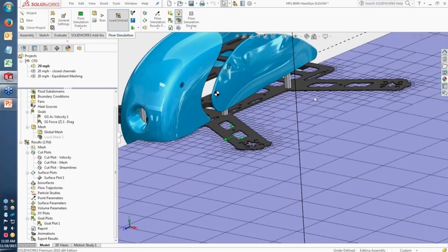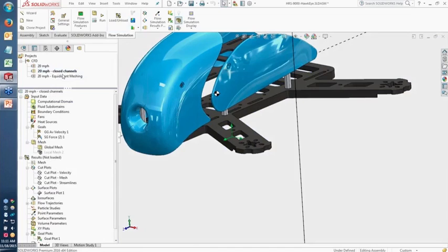But in this particular case, you probably can imagine that the real analysis would not allow airflow to have any kind of passage through these slots because there would be fasteners and other components filled in there. So if I want a quick way to ignore all those little slots and not have to worry about meshing them well to get a realistic result, I can immediately check the close thin slots option and it'll turn off all of those cells. So here I can switch to this other version of my analysis here.